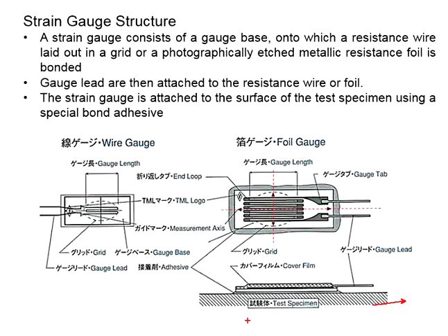The force here leads to changes in terms of the strain, and this strain shall be transferred to the adhesive and then to the base of the strain gauge and then to the sensitive element. The test specimen will elongate first, followed by the adhesive, then the gauge base, and then the sensitive element.